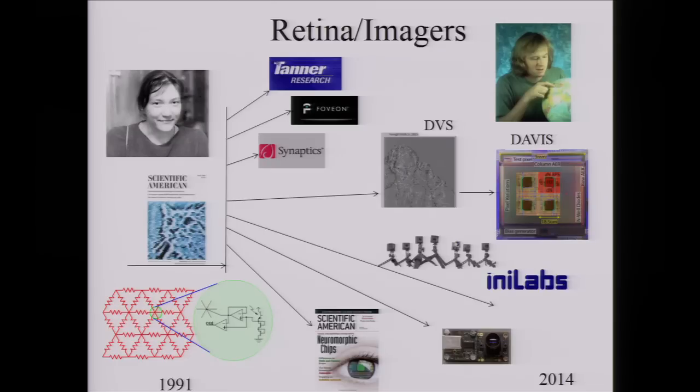And so it basically consisted of a log photoreceptor where the output now drives a resistive grid, and this resistive grid computes the spatial temporal average of the surroundings. And by taking the difference between the output of the photoreceptor and also that of the spatial temporal average, you can get the edges, if you can see, of the object.